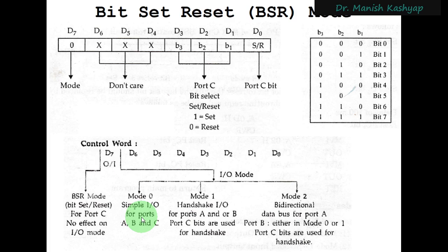So it will be your headache. So mode 0 is something like that, right? Here the microprocessor will have to take care, not the 8255 PPI. The microprocessor will have to check the status of this externally interfaced peripheral, but the data will be transferred through the 8255 PPI. So this mode 0 is applicable for A, B, and C, all the ports, where all the ports can be programmed as either input or output port in any combination, right?